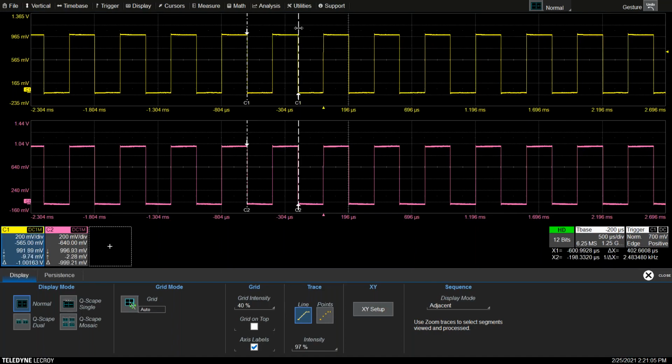I'm just using the cursor, and I could use the knobs, but I'll use the mouse to do this. Now we can see the delta difference displayed here in the waveform descriptor and off to the right. Of course, you'd make timing measurements. There's the difference in time between the two cursors. By the way, the cursors show you the time from the trigger.